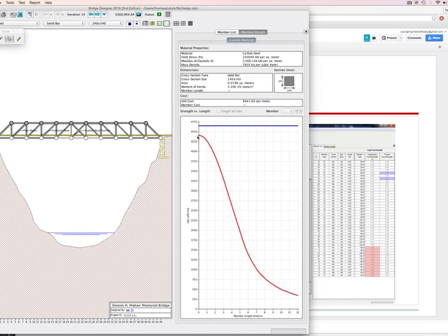Here in compression, when it's short, like a foot, look how strong it is. By the time you get down to 12 foot. So again, compression is very sensitive to length. Tension is not. You can have hollow tubes in compression. Doesn't matter. Good way to save money. Tension, it would matter. The materials you make it out of impact both of them. Okay? So these are all good things to remember.